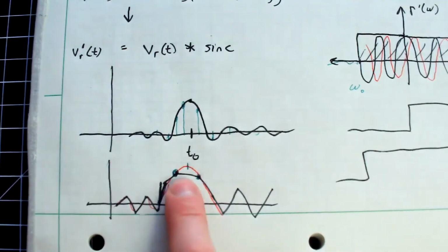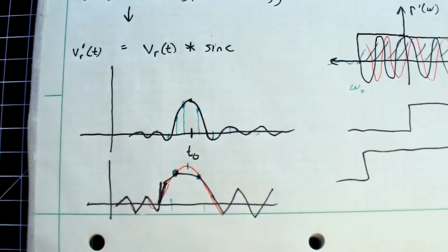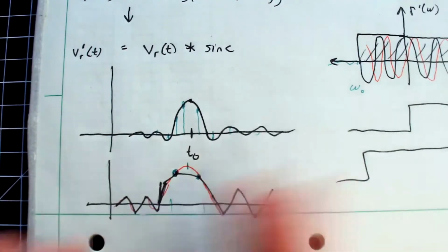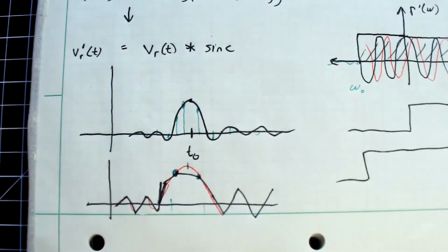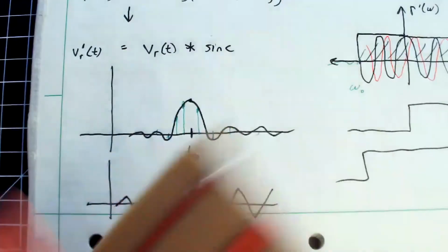So we saw how that seemed to introduce a lot of uncertainty in our lab measurements, and it was pretty bad, right? Because this was almost half a nanosecond of time spacing, which corresponded to a couple of centimeters of uncertainty when you tried to measure the length of something like this.